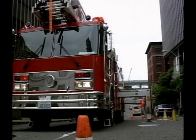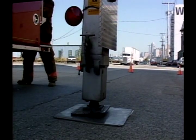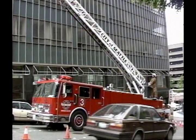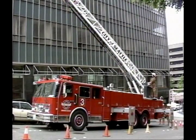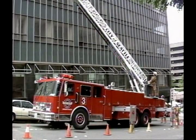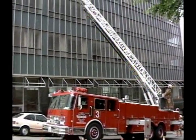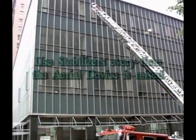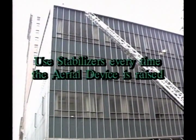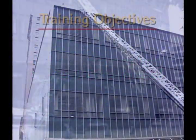Stabilizing the apparatus is an important first step in preparing the aerial device for use. Stabilizing means to broaden the base of the vehicle so that it is less likely to tip over when the aerial device is extended. Although stabilizing is more critical in certain situations than in others, it is recommended that stabilizers be used every time the aerial device is raised from its bed.